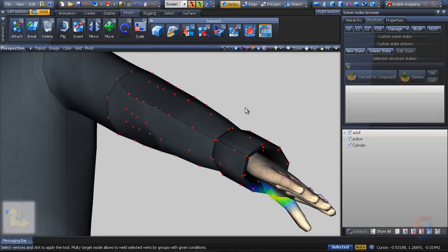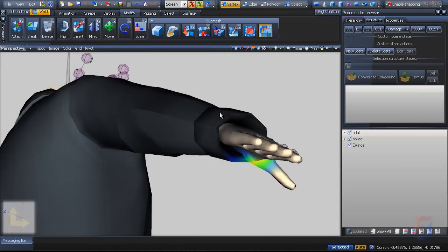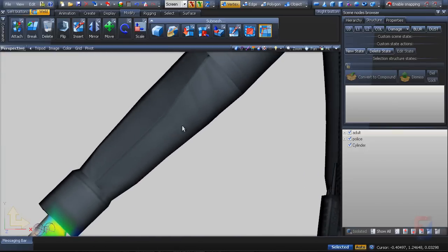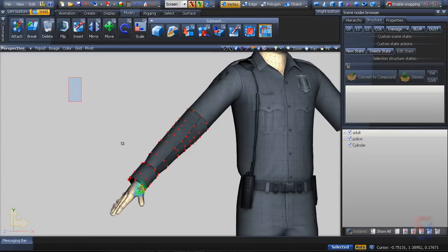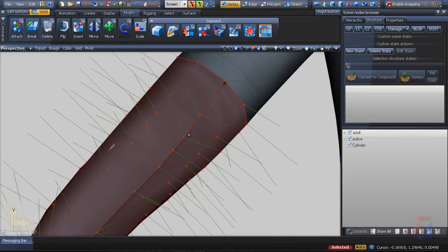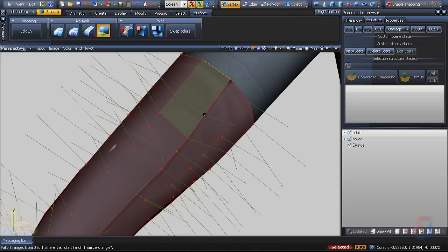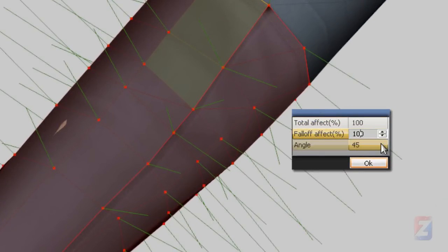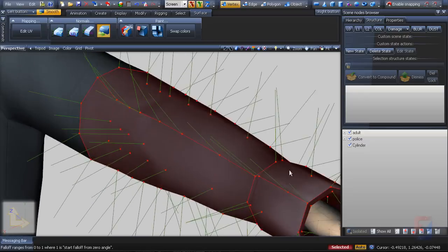Deselect. And disable the wireframe in viewport. You see the shading is sharp, and inaccurate on the sleeve. We shall fix the most of it now. Enable the wireframe and outline again. Pick Surface, Normals, Smooth tool. Hover and click. These are default settings I use. There are still some pairs of normals on vertices. Hover and click again. Fine.